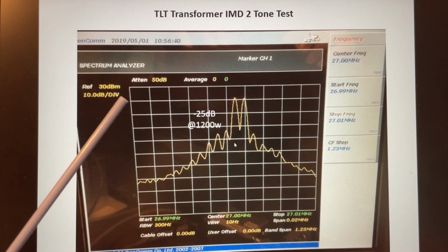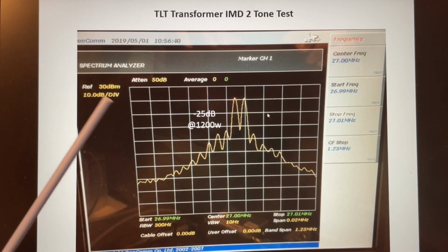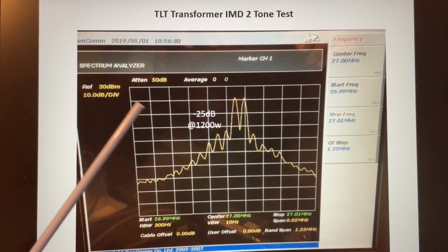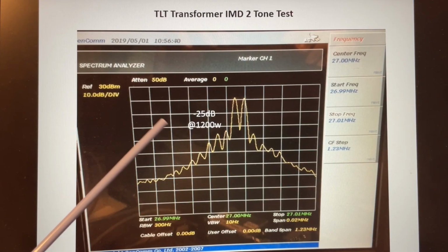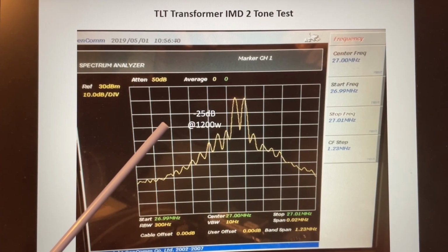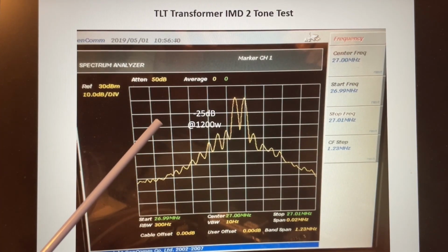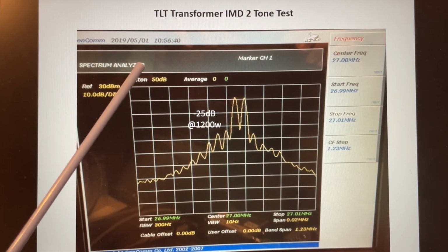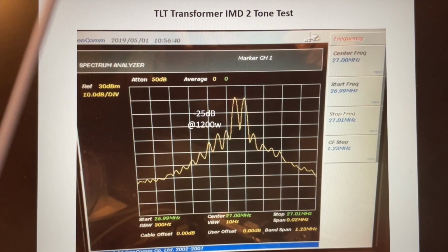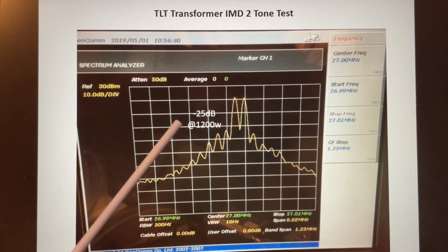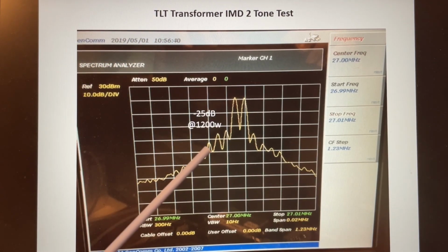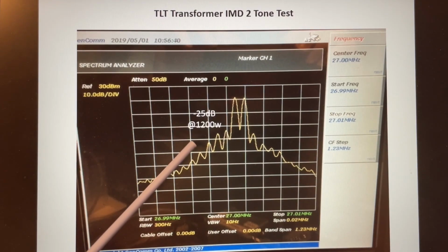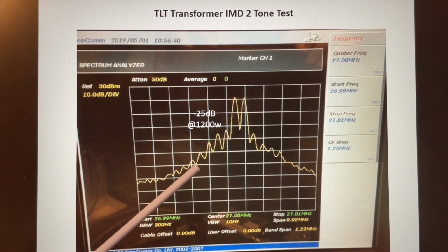This is a good measure for basically sideband, how much bandwidth you would occupy on each of the sidebands that you're transmitting on. So this is another good important data point, the two-tone test with the intermodulation distortion. And I have a separate video on this, and I'll post that under the video. I'll put some of the relevant links that you can go back and check if you haven't seen these videos before.